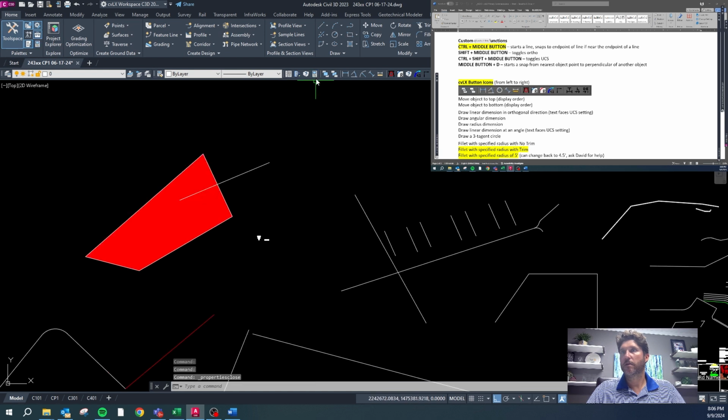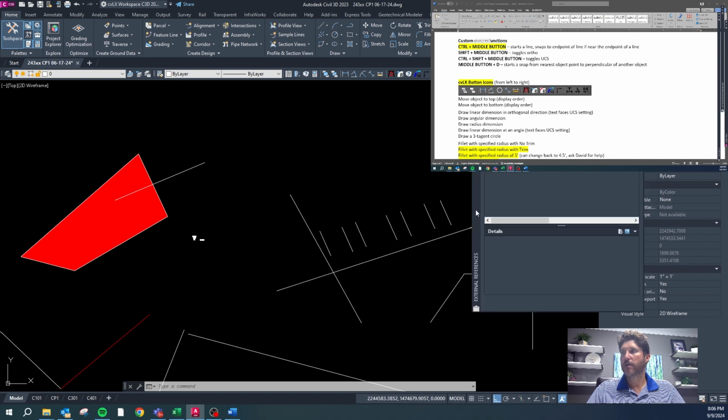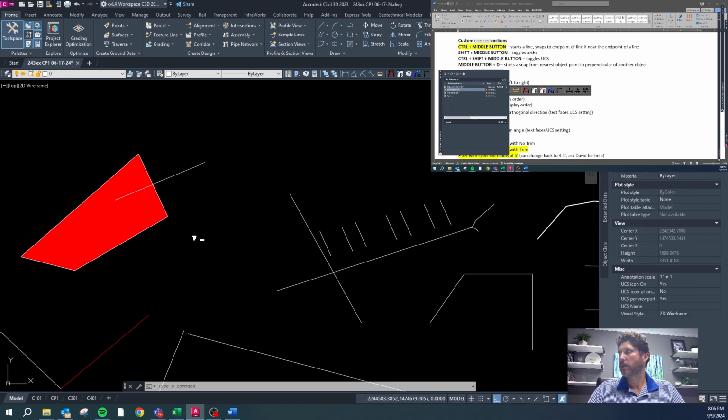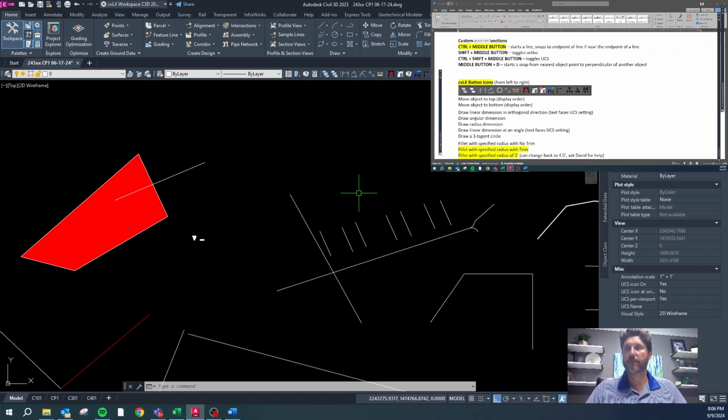Then here we've got the Properties tab, which is this guy. You'll definitely want to have that on all the time. So I like to open up multiple of these dialog boxes. I usually have properties, external references, which I think is IM to start for images. I have layer properties, and then the show tool space. And I keep those open on a screen to my left so that I have a big screen here to work with. And then I can view all this information on another screen.